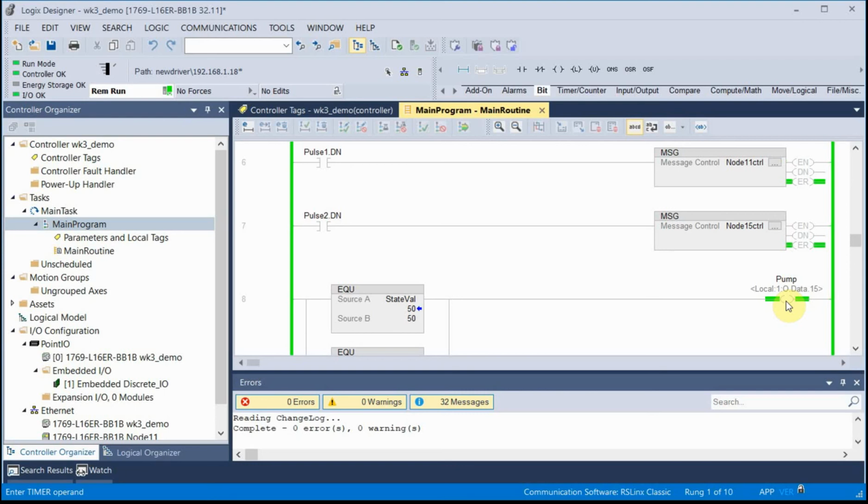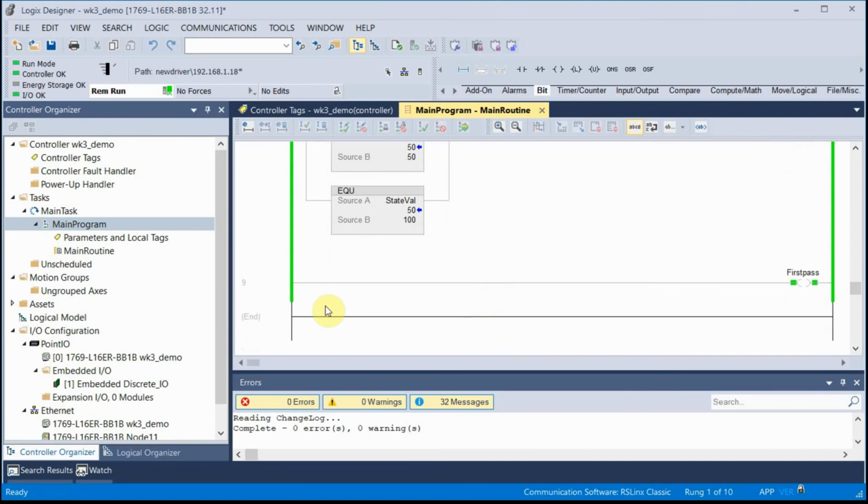I don't like the idea of any kind of coil current rushing through the relay contacts inside the controller. They're expensive to fix. If I have an external relay and burn it up, that's $20 or so versus the cost of a new controller or getting it fixed, which is high. Okay. So here's the basics of it.